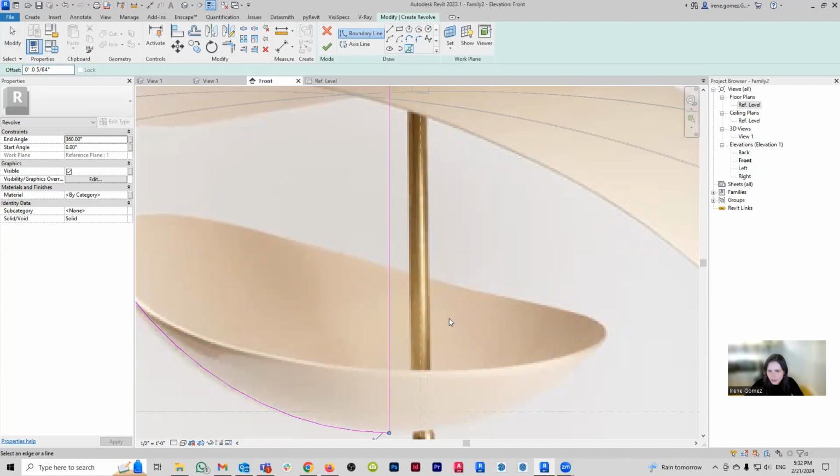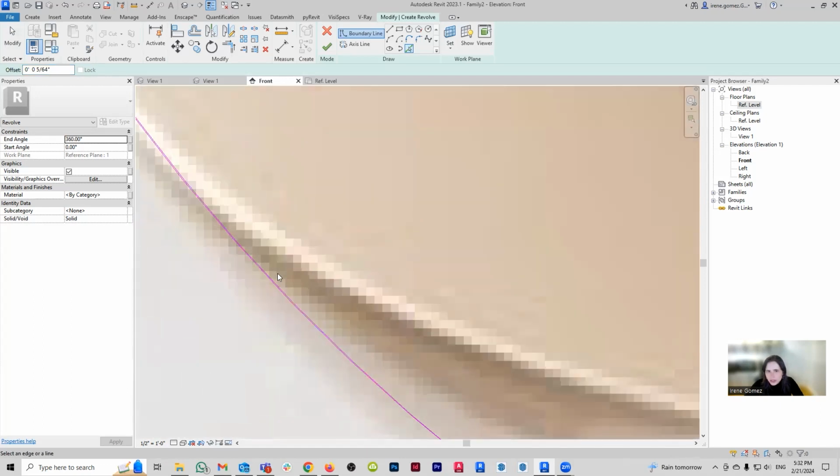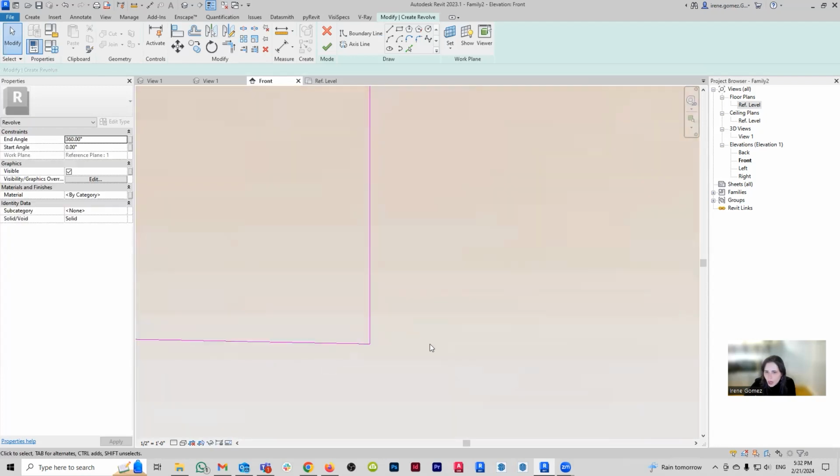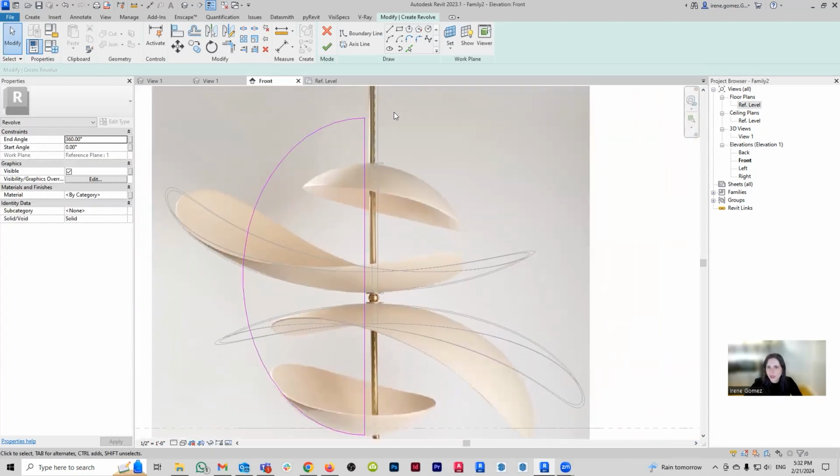So 2 millimeters. And we're going to go offset inside. Ooh, did it even make it? Man, Revit, are you okay? I don't know why offsets give such a hard time. I could try to make it a little bit thicker because I think that the size of the offset itself would be part of the problem. Let me actually try that. What happens if I say 5 millimeters instead of 2?